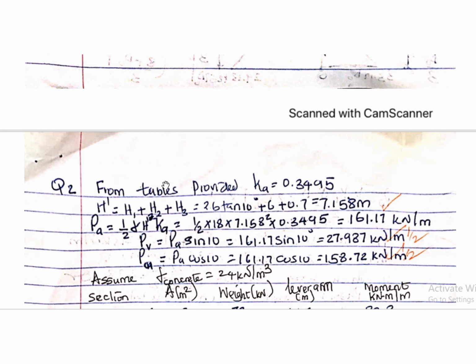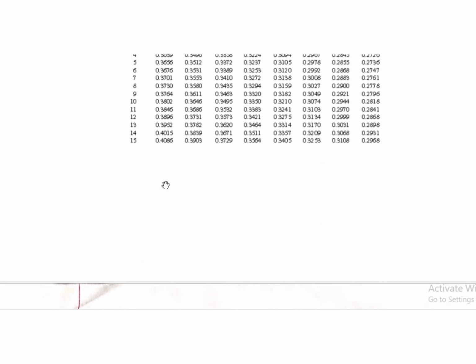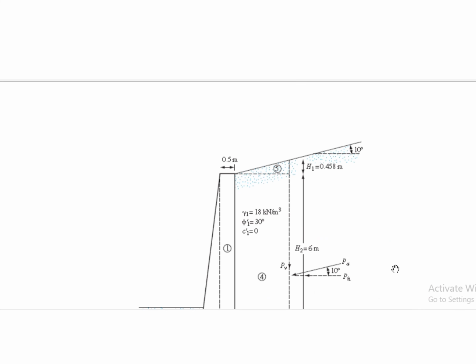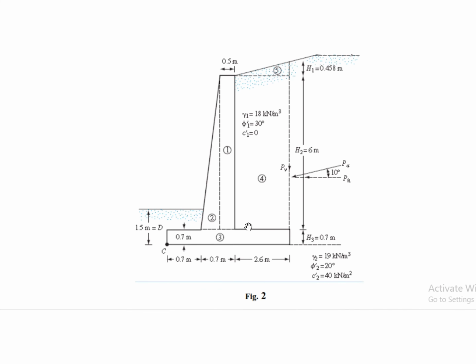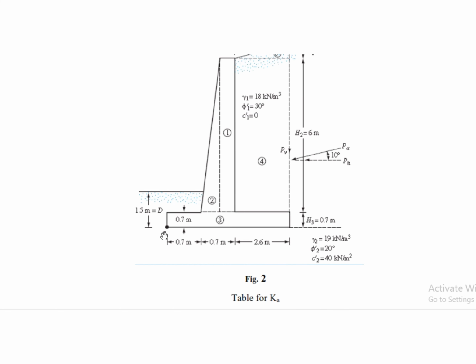So the part of soil, I think, is part 4. So don't confuse the unit weight of concrete. Sections 4 and 5 will use the unit weight of soil, and the rest of the sections will use the unit weight of concrete. How to get the center is just, these are just triangles. For example, here the centroid of section 2 is 2/3 from this edge, if you can see where I'm pointing.